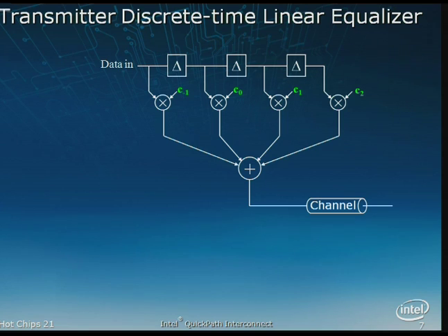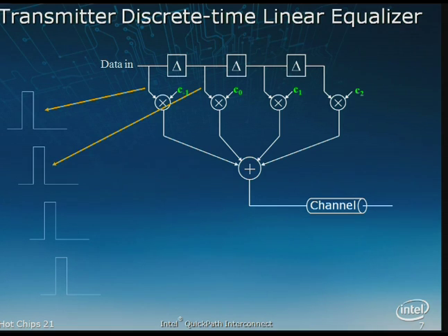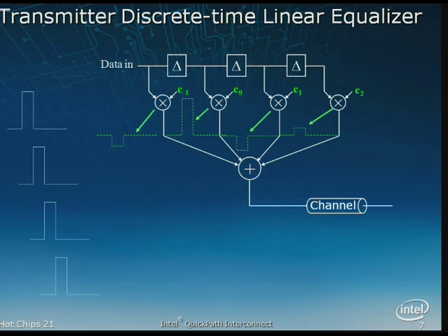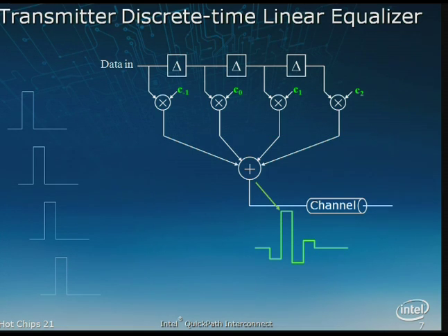A circuit which basically provides some type of coefficient or multiplier, and then a summer. And so you start off with a simple input of a pulse, and at each delay point, you just have that pulse replicated. Then, as that pulse is fed into that multiplier, a coefficient takes that signal and does something to it. And it could be a negative multiplication or not. And then at the very end, the summing logic basically puts the pulse back together again.